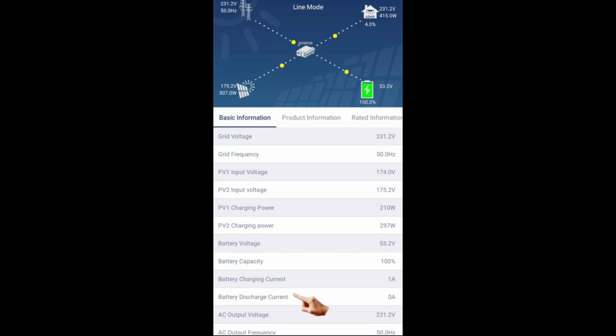The battery discharge current is the number of amps being drawn from the battery while discharging. An example: if you are discharging a battery and the battery is 120 amp hours, discharging from full, it will theoretically take approximately 3.5 hours to discharge at 30 amps per hour, because it must keep 10 to 20% power in the battery.